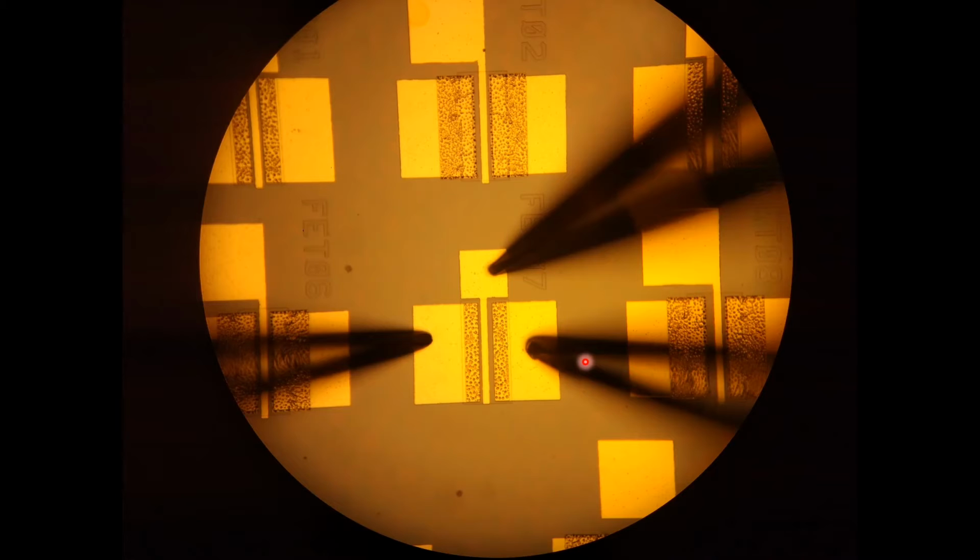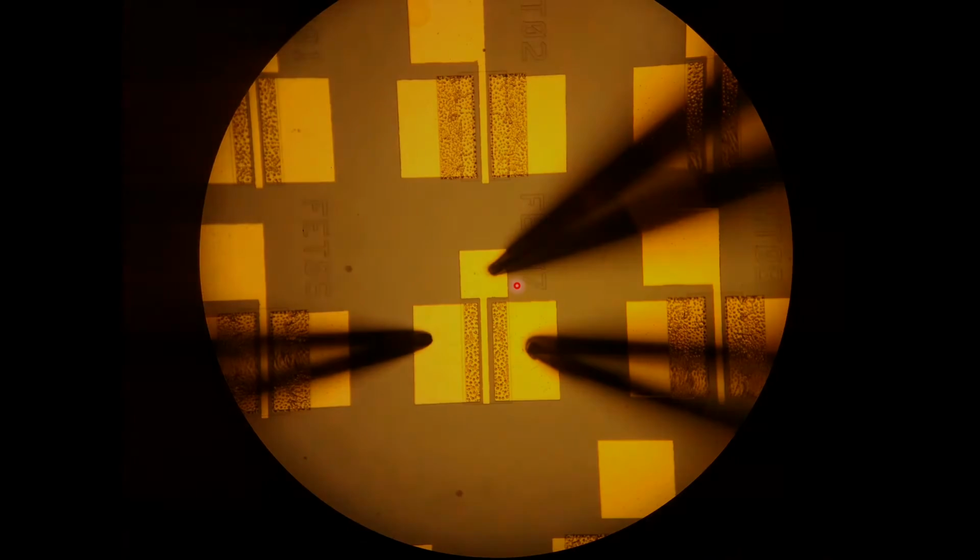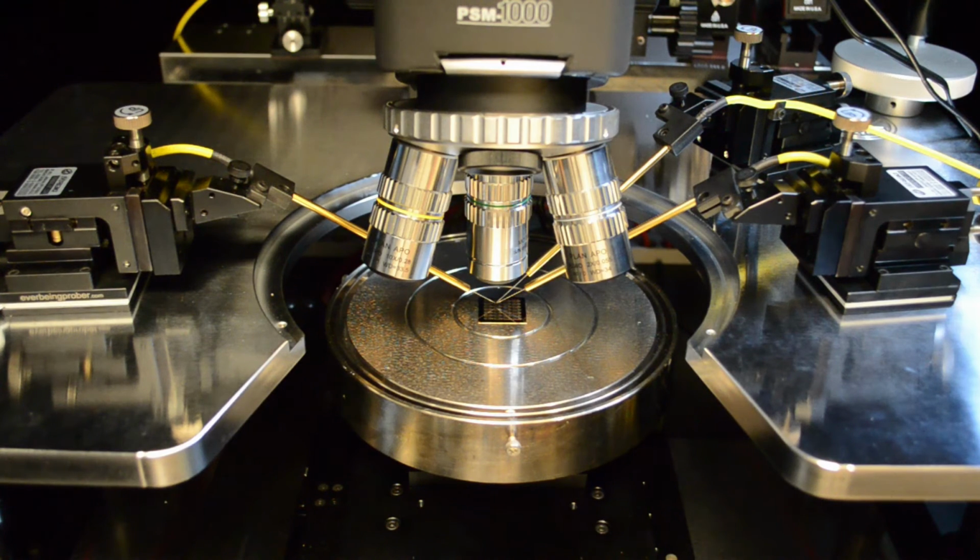Before moving forward with the measurement demonstration, I want to point out that the contact pads themselves have a nice smooth finish, but we also see these rougher regions that are represented in each and every one of the devices on the wafer. This is actually intentional and highly desirable, as it is a visual cue that we have successfully performed contact alloying at the source and drain terminals. Contact alloying provides us with a low contact resistance ohmic contact for those source and drain terminals, which is necessary for successful transistor operation. So let's go and walk over to the semiconductor parameter analyzer and take a look at how setup is done for a measurement.